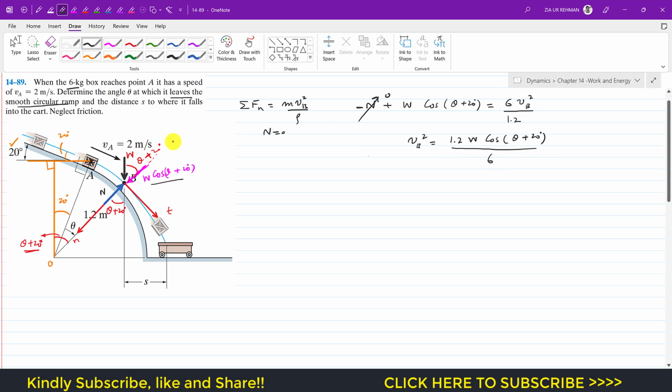Now we know that the weight is mg and the mass is 6, so this will be 1.2 W, and W is 6 into 9.81. So 6 will cancel out, and Vb square will be 1.2 into 9.81 cos of (theta plus 20 degrees).